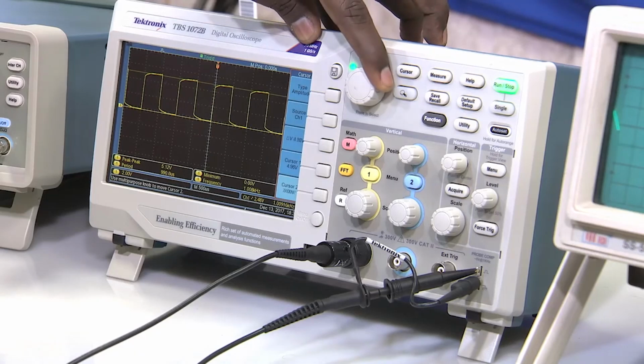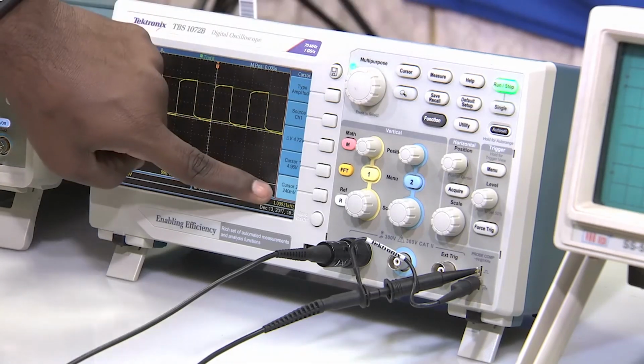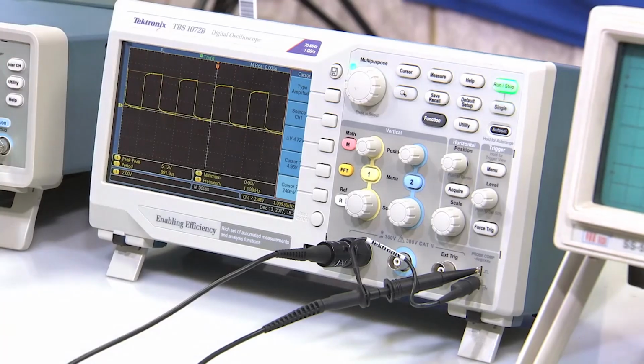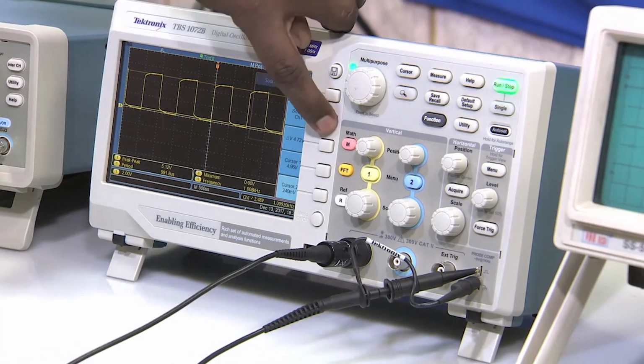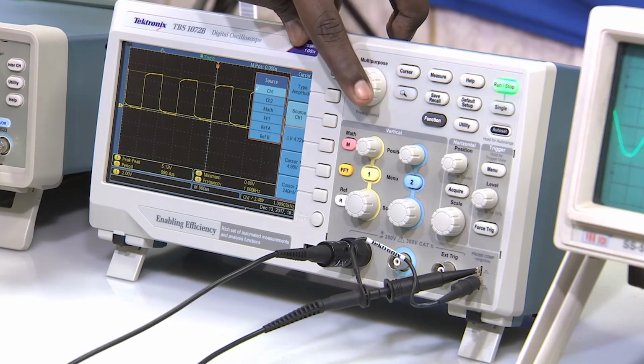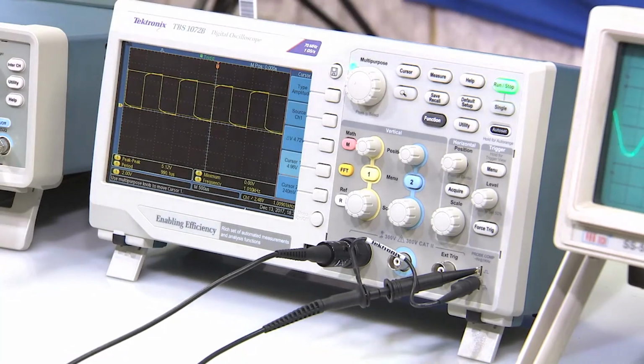Now, you can measure the voltage at cursor 2 and the voltage at cursor 1. So, you can see cursor 1 and cursor 2 each have a voltage, and you can measure the difference. This is the use of your cursor, right. You can also choose the source, channel 1 or channel 2, and change the mathematical function: FFT, reference function, reference A, reference B. So, a lot of options are there when you get a digital oscilloscope.